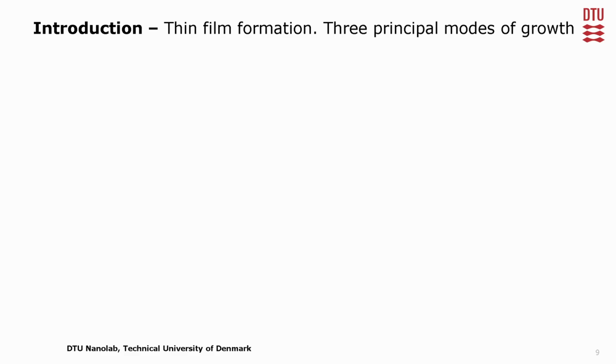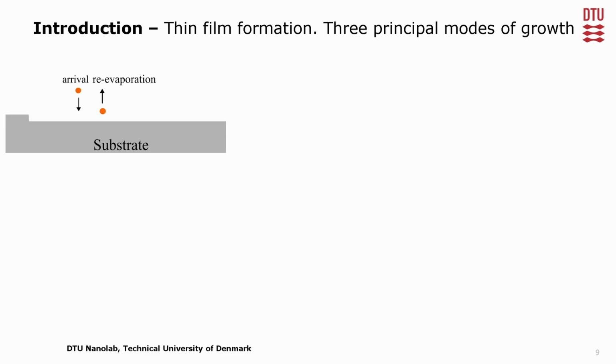Alright. Now I'm going to talk about the mechanism of formation. Imagine you have a substrate, possibly with defects like terraces, roughness, or grains. When an atom arrives, different things can happen. The incoming atom can re-evaporate immediately, or it can travel along the surface and meet a neighboring atom, creating a metastable island. While these islands are small, they are not very stable and can separate quickly.